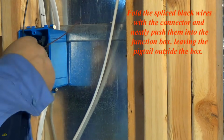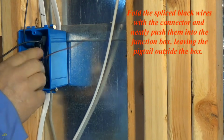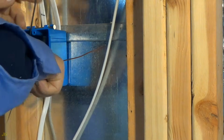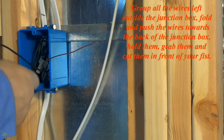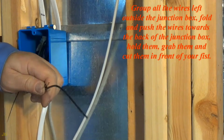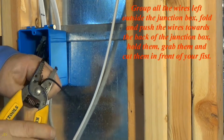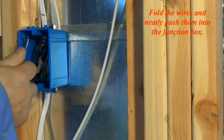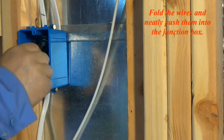Fold the spliced black wires with the connector and neatly push them into the junction box, leaving the pigtail outside the box. Group all the wires left outside the junction box. Fold and push the wires towards the back of the junction box. Hold them, grab them and cut them in front of your fist. Fold the wires and neatly push them into the junction box.